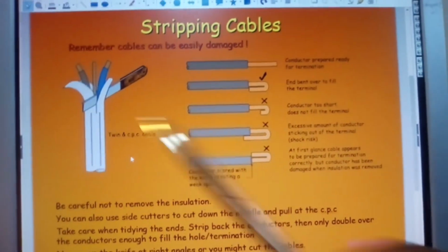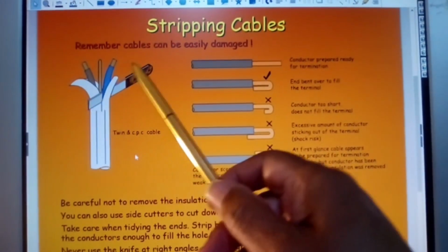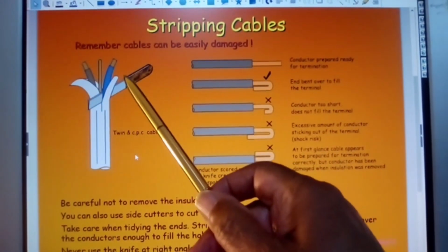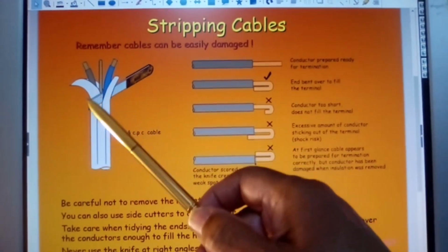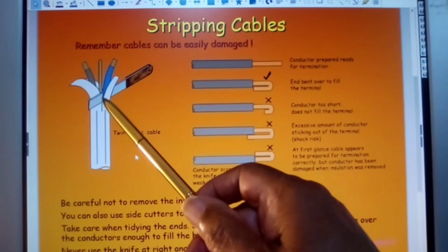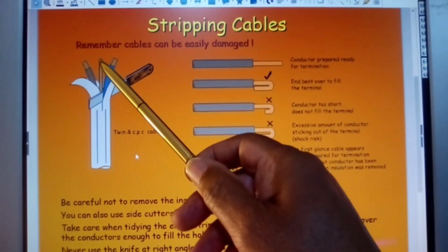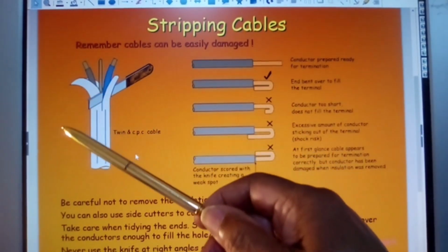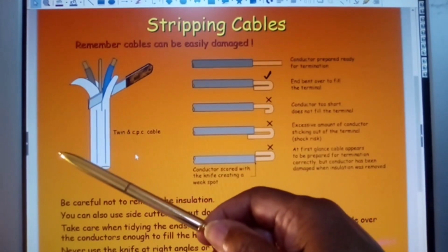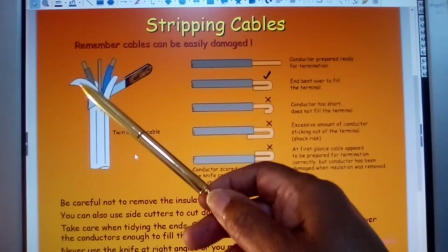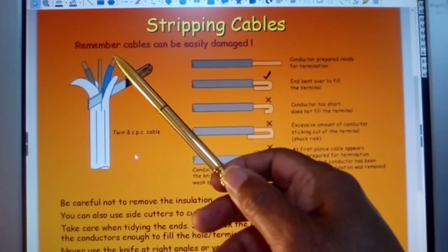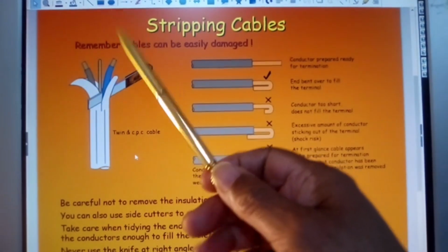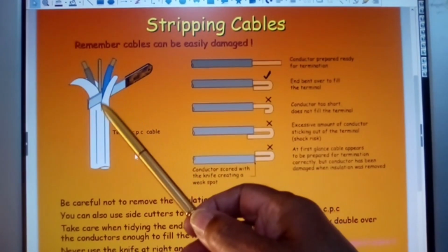Right. Never split a cable like this. Never, ever split a cable like this. I know I'm showing you this here, but when I looked at this myself, it's not how I would have done it. In my experience, you would simply use the earth conductor and pull it down safely, providing you have enough space. You would make sure you did that before you terminate your conductors at the terminal point. But don't ever split a cable down like this.